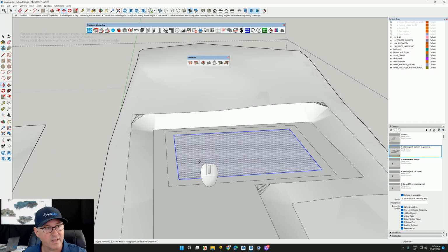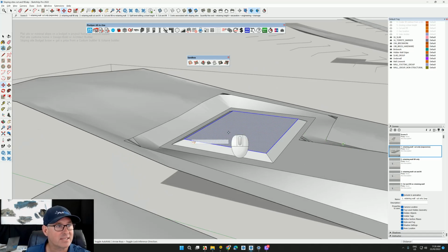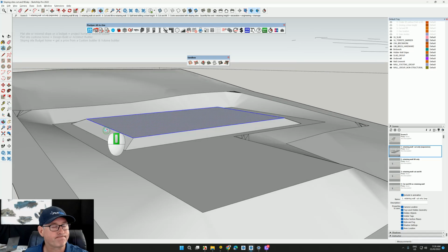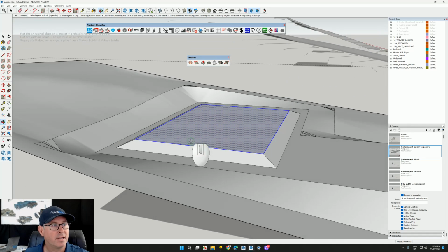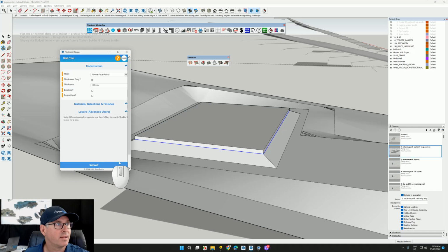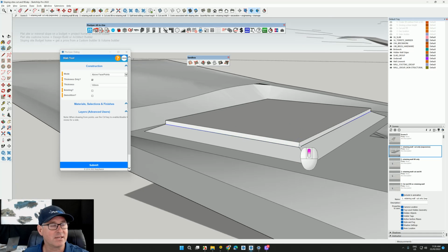And I won't move again, push my up arrow. You'll notice that now I actually could situate my slab on top of an area. Right, therefore right click, slab, create slab. And now my slab will be sitting on top of a sloping ground.